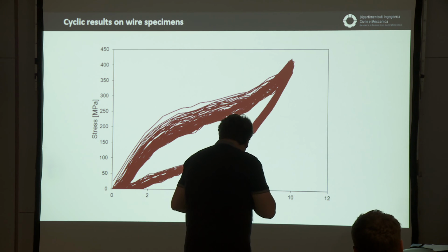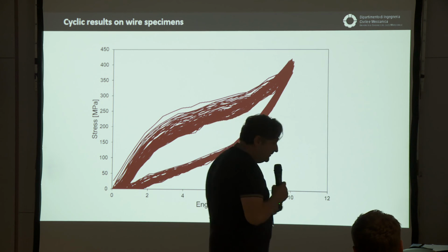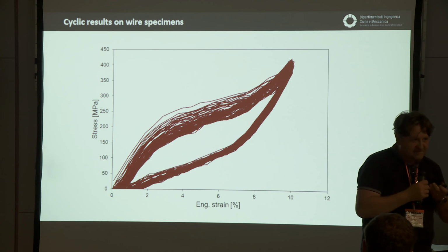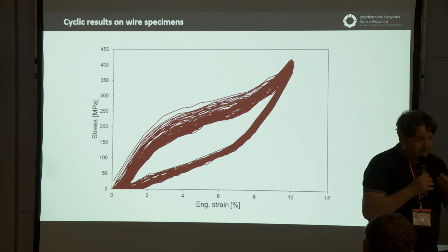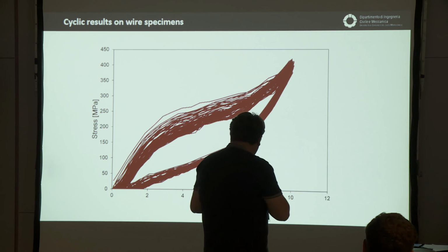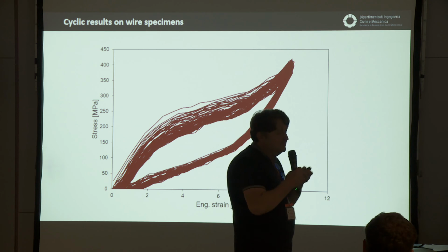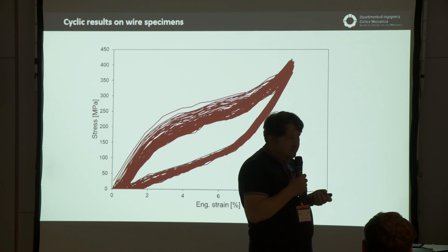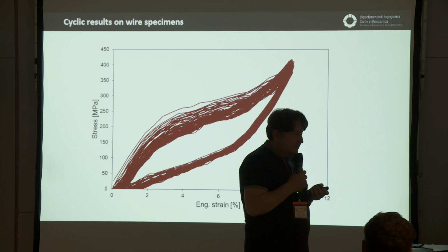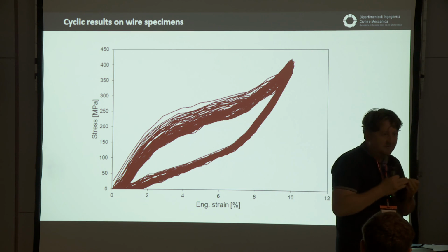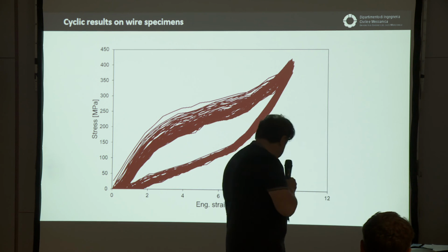If I have a quantity of martensite which is not able to recover into austenite, this is the loss of part of the memory effect, which is the difference between the martensite able to recover into austenite and the martensite that is stable. In terms of spectrum, it's impossible to find this, because the peak is always the same, and you can change the amplitude, but the position is almost the same.